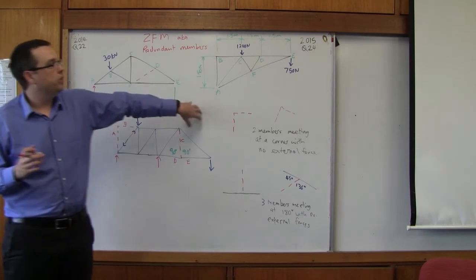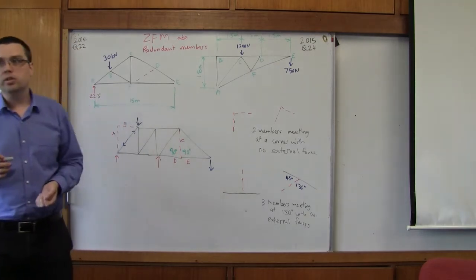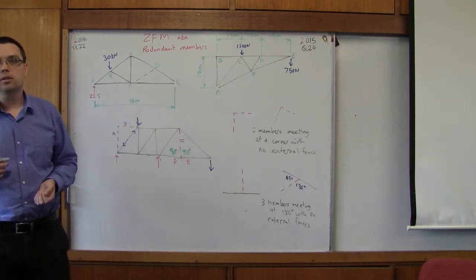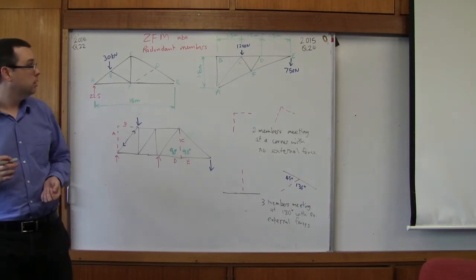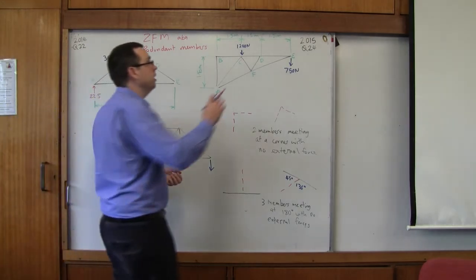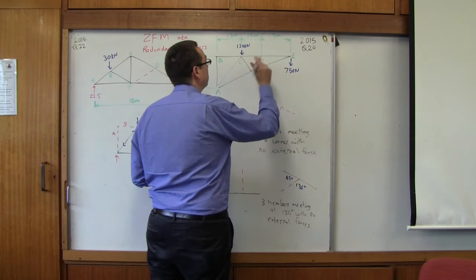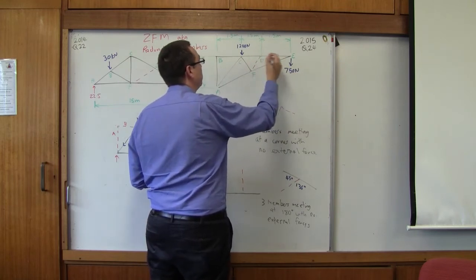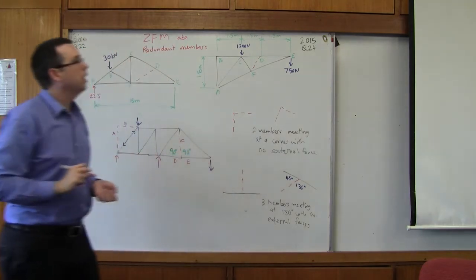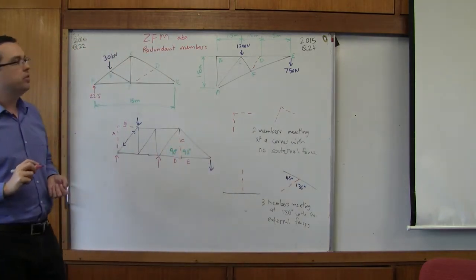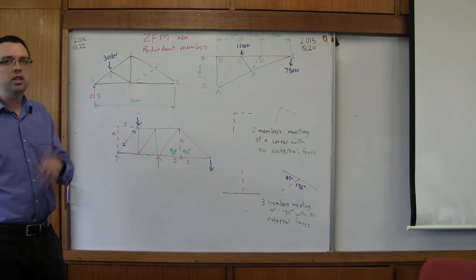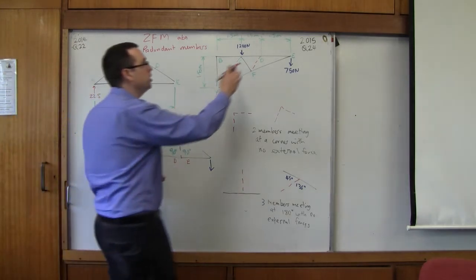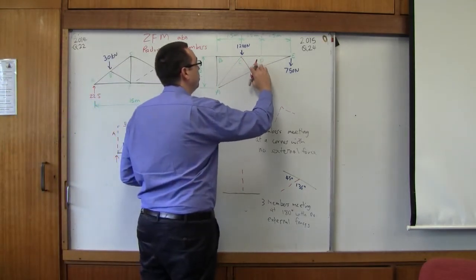On the 2015 question, where is the zero force member we can see? It's FD again, yeah. Because this here is a supplementary angle, okay? And then what happens now? So when FD disappears, if we just imagine that FD isn't there, for the moment I'm actually going to just remove this from the whole drawing.